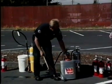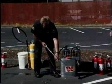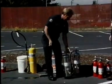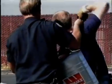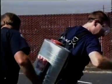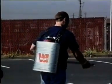There are two general types of water extinguishers, pump tank extinguishers and stored pressure extinguishers. Water extinguishers can only be used on Class A fires. To use a pump tank water extinguisher, carry it to the location of the fire, pump the handle with one hand, and direct the water stream with the other.